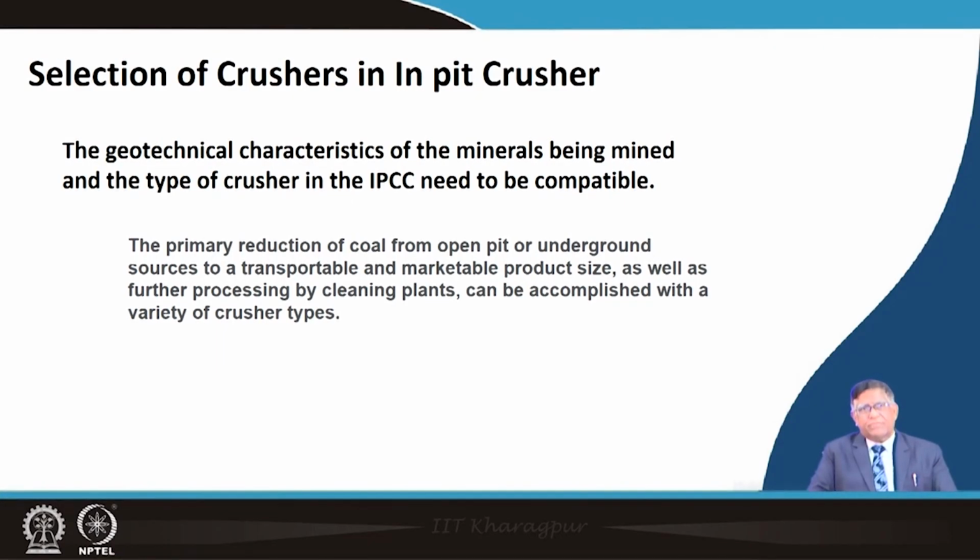Now, if you are using a conveyor belt with the crusher, how will that conveyor belt cope with that sticky material? So, when you select the crusher, we will first look into whether the crusher strength is adequate. Two situations may arise. One is that you select a crusher which is very heavy, using a lot of energy, but your material is very soft. Or the other way, you take a crusher which is very small, and it cannot break the rock, so it will go on repeating the attempt to break one rock.